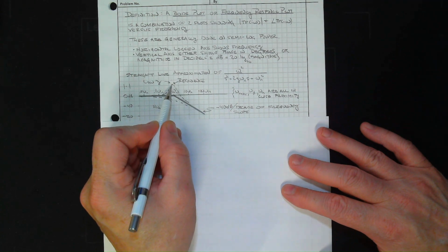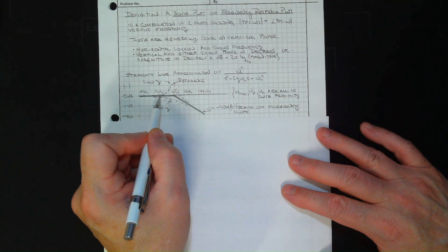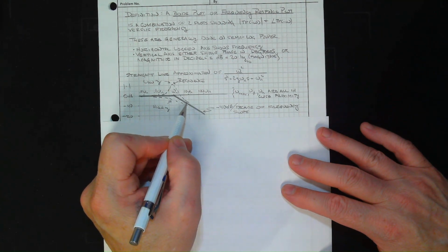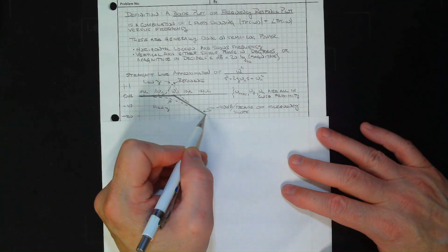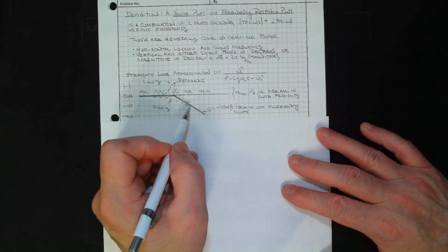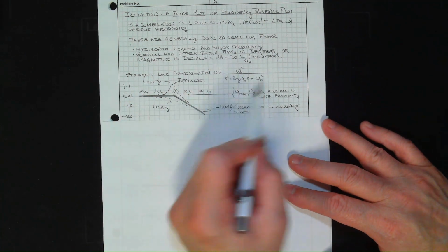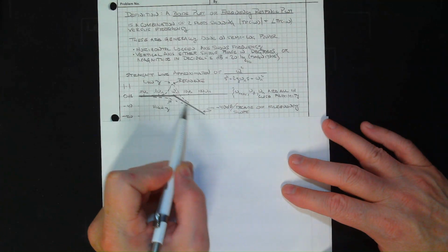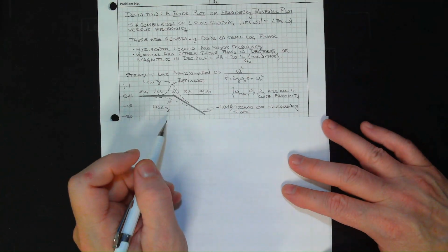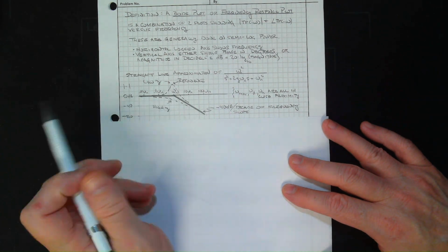For low damping, you're going to get your resonance somewhere in the neighborhood of omega n, and it goes up, and then as it comes down, it'll asymptotically approach this minus 40 dB per decade line, or minus a factor of 100 for 10 times increase in frequency. All right. So any underdamped system, here's our straight line approximation, where we're just kind of ignoring the level of damping and stuff. And outside of the resonance, it's a pretty good approximation, actually. Okay, so there's magnitude, and we've seen that. So the work we've just done has shown that.